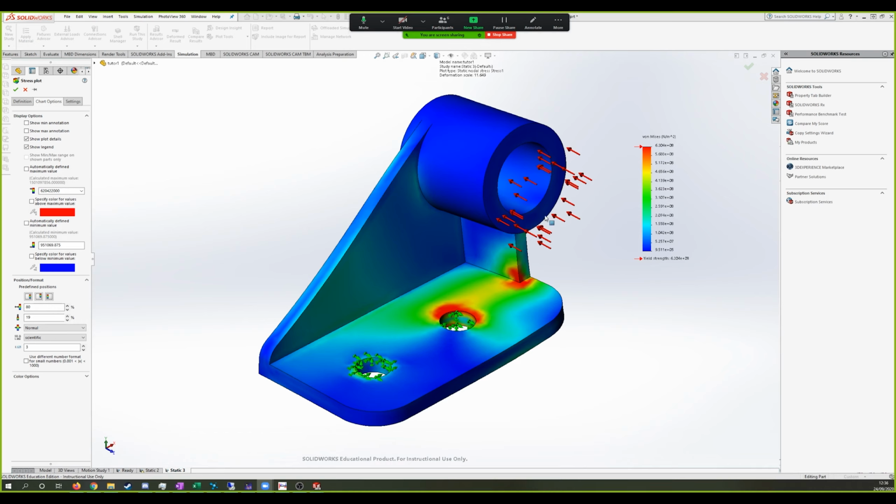What was the thing you showed me here yesterday with changing the stress plot options? Right click on the graph and edit. I've done that. It's here on the left. Oh yeah, right. So make the bottom one 0, and the top one, click the arrow and make it your yield stress. Then click show max. You can do show max if you want, I usually don't because it moves.